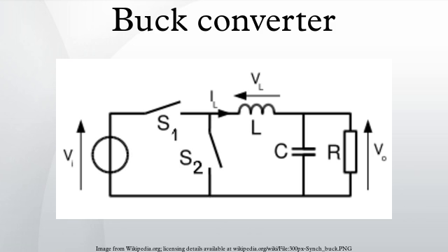As can be seen in Figure 5, the inductor current waveform has a triangular shape. Therefore, the average value of IL can be sorted out geometrically as follows. The inductor current is zero at the beginning and rises during turn-on up to ILmax. That means that ILmax is equal to the following. Substituting the value of ILmax in the previous equation leads to the next expression. And substituting I by the expression given above yields another. This expression can be rewritten as follows.